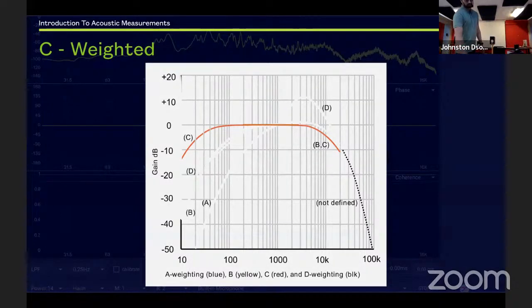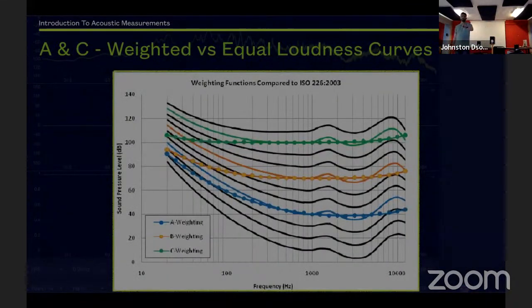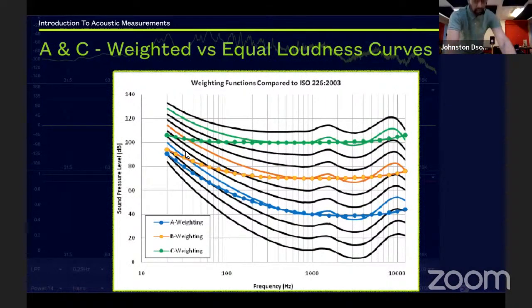Now next, this is the Fletcher-Munson curve, and you see there are these dotted lines. Forget the yellow dotted line. Look at this blue dotted line here, and the green dotted line. The blue dotted line is basically the A weight scale. It corresponds to what we human beings listen to at about 80-85 dB SPL. As the sound gets louder and louder, our hearing also flattens out, and that is what the C weighted scale relates to.